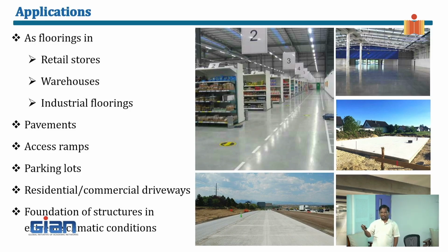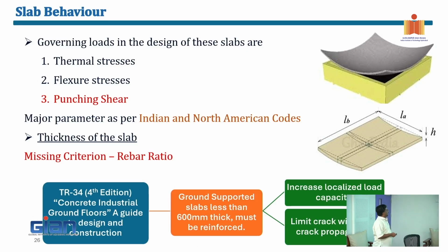And industrial structures will be in a very corrosive environment. And most important, as Professor Gangara was telling, where did GFRP initially find its application? Deck slabs, and also, most importantly, hospitals, right? Yes. When you want electromagnetic neutrality, nowadays we have so many hospitals, we don't want that interference. So we can do such kind of slabs, but then you have to do it properly.